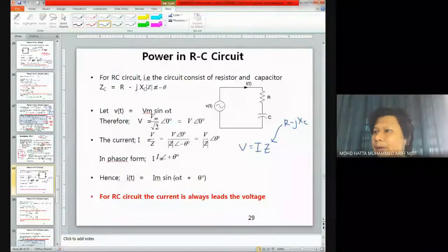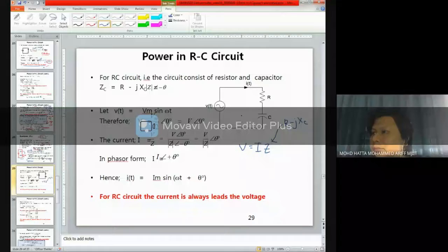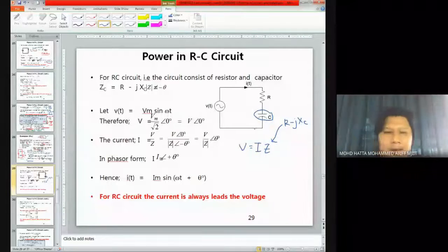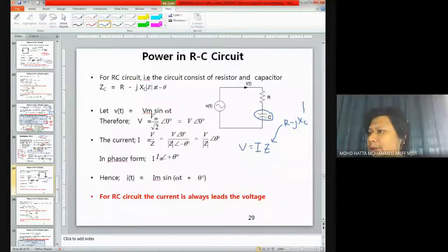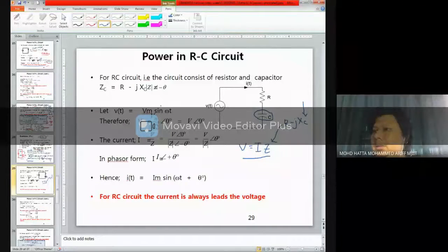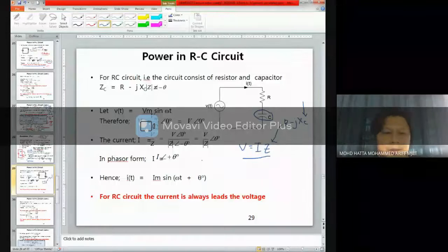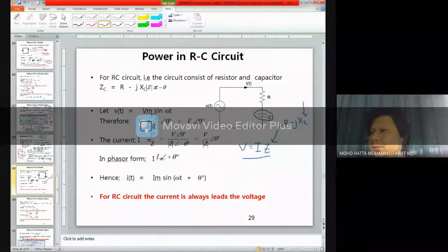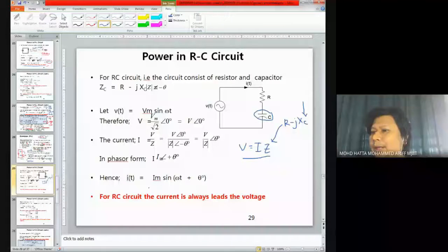So if you come across this kind of loads or this kind of circuit arrangement, first of all, have a look at the value of capacitor over here. If it is in farad, you need to find what is the frequency, and also try to calculate what is its reactance value, is Ohm's law. All right, I think we did this one in previous lesson. So using Ohm's law, we can find I, the current.